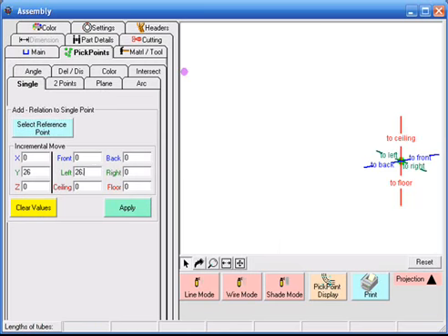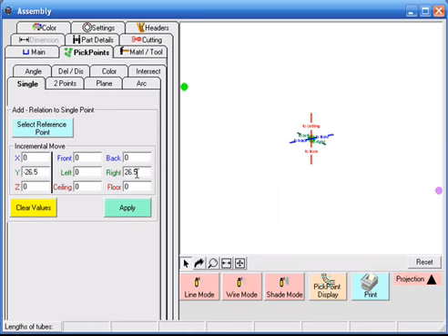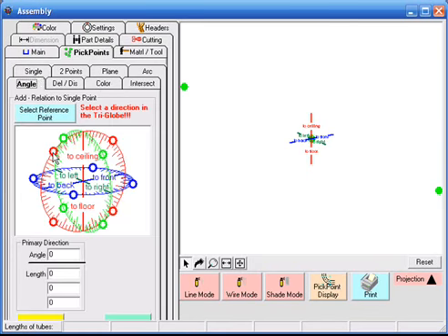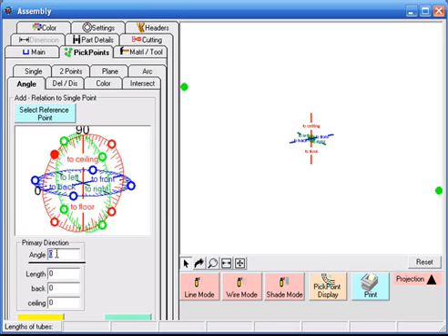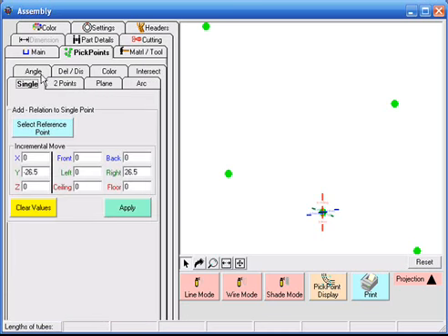We have started by defining the base points of our first pillar. Next, we are going to define points by using angle. We can select the quadrant, angle, and distance. Back to single, and we're going to create 2 more points towards a ceiling of 16 inches.